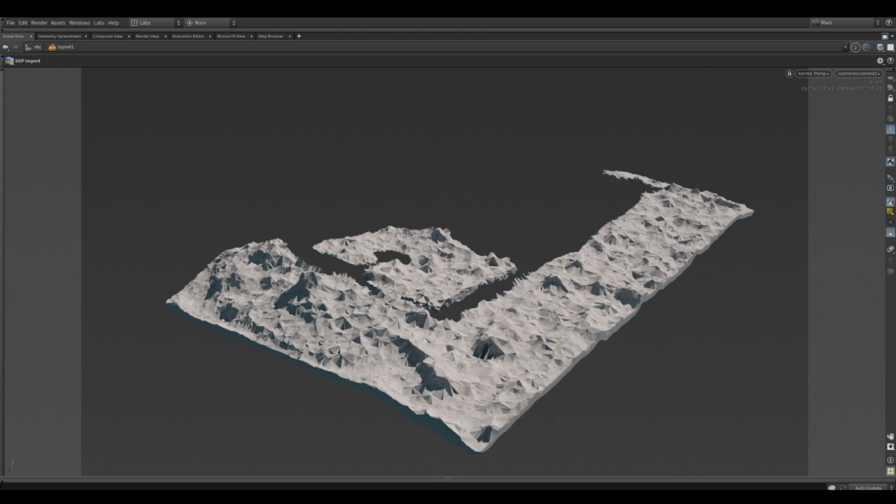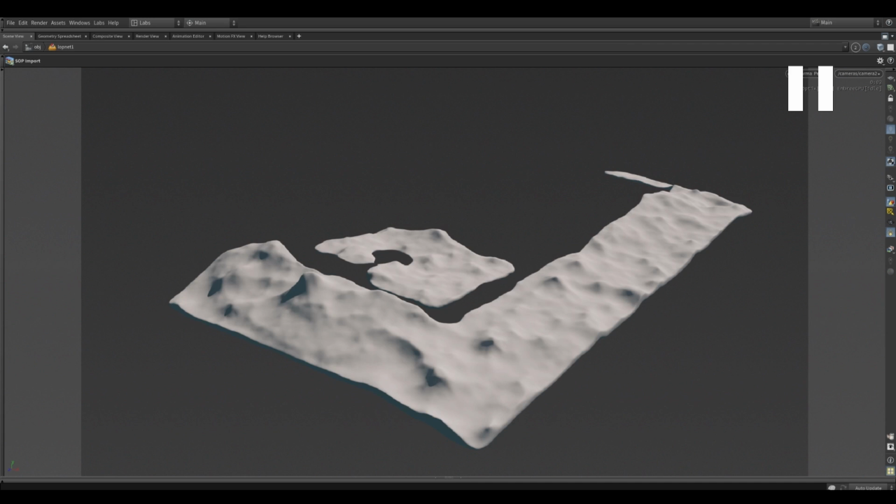So what this is doing is, after the conversion from VDB, the geometry is a lot fatter than the original geometry. So we can recast the fat geometry back onto the original geometry, resulting in this low poly look. That's because when you do recast, a lot of the points will be cast onto the same target location, creating this stretched, tinted look. We can fix that by applying smoothing on this again. So it will result in this kind of shape. Now the surface of the new converted geometry is much closer to the original surface.